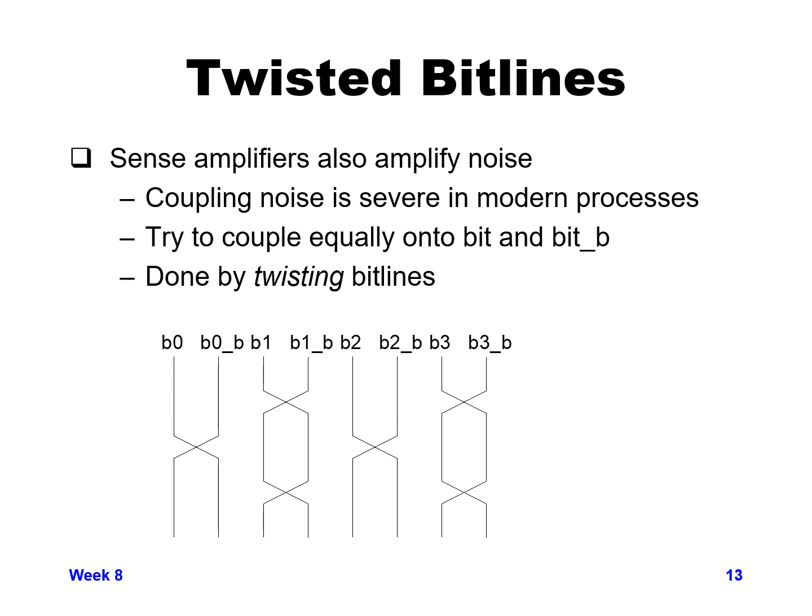And so in effect, any noise from coupling capacitance will be equal from either side for bit 0 and bit 0 bar due to bit 1 and bit 1 bar. They should see the same amount of coupling noise on both sides of the bit.